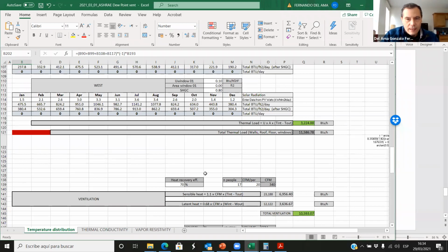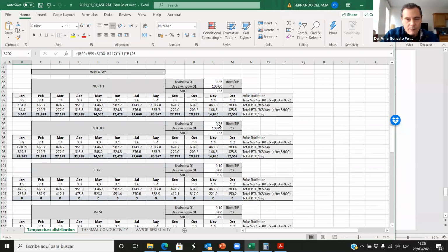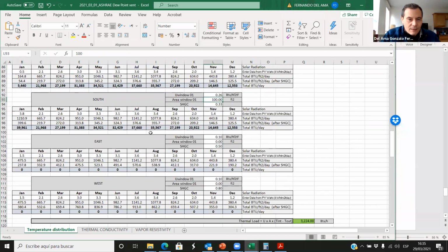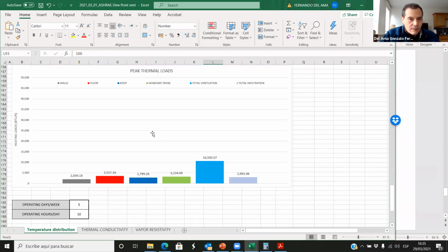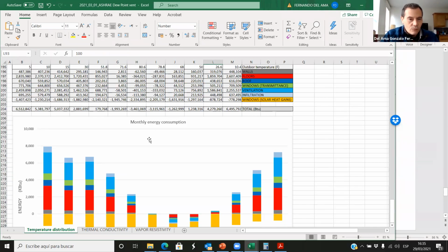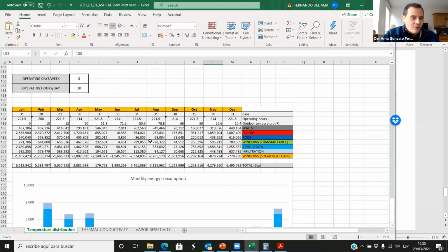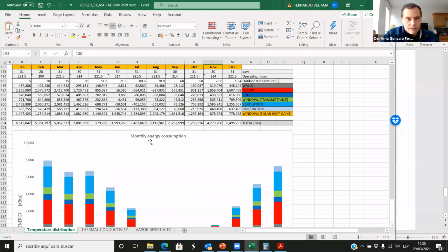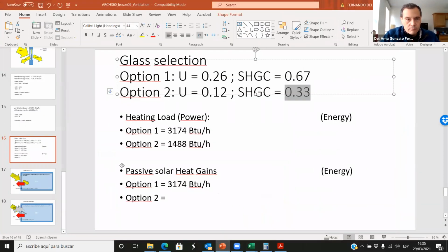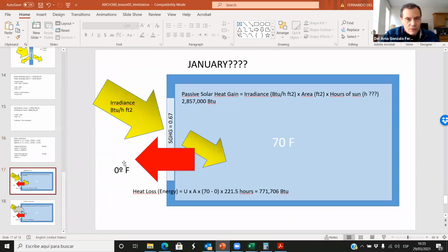So depending on what kind of glass we select, the amount of the area, the orientation, it depends, but we need data, and I think this is something easy, and we can use this to analyze. Okay, am I doing something good, or am I doing something that is nonsense? Well, it's not bad. And opening windows to the south, it's always something that works.